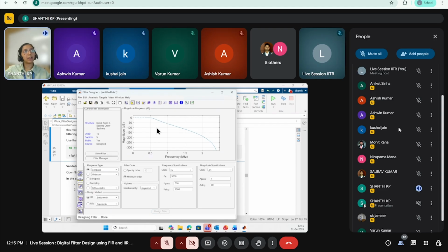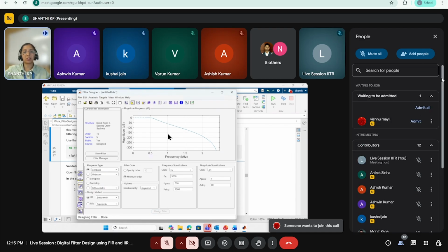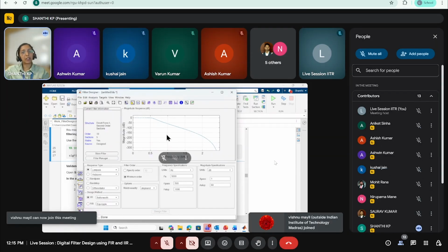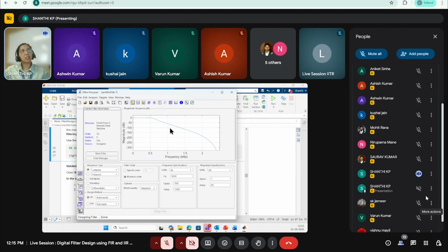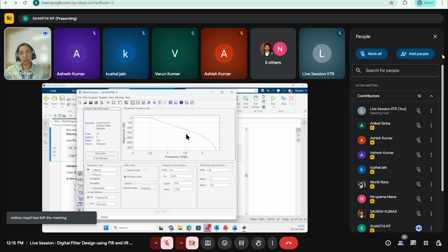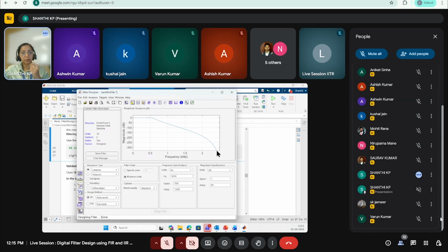And between 0.5 and 1 kilohertz, which is our transition band, the response transitions downward. This is normal because we intentionally left a gap between the passband and stop band, right? So there's a drop here, and beyond the stop band, which is greater than 1 kilohertz, the magnitude continues dropping well below minus 60 dB.